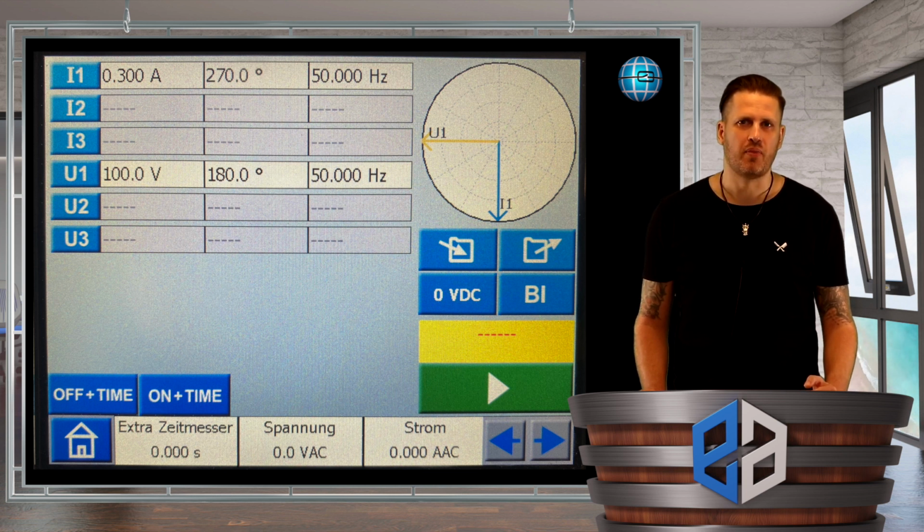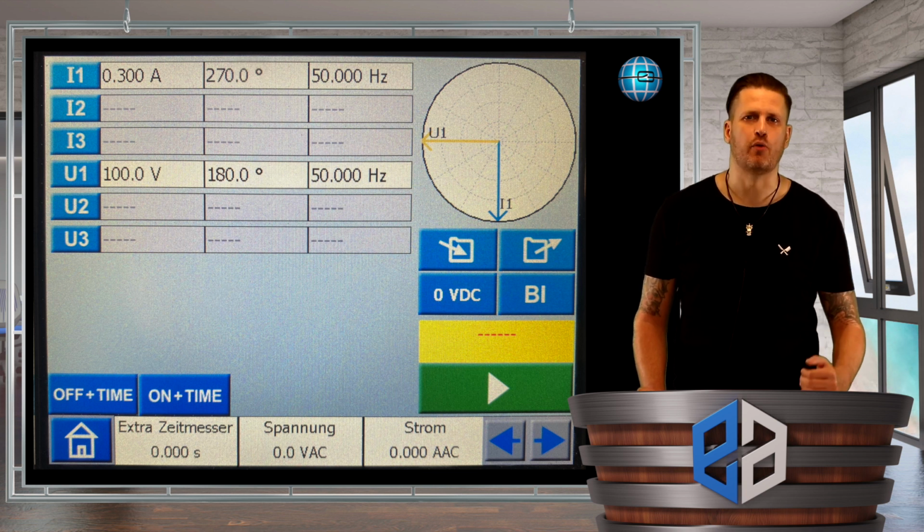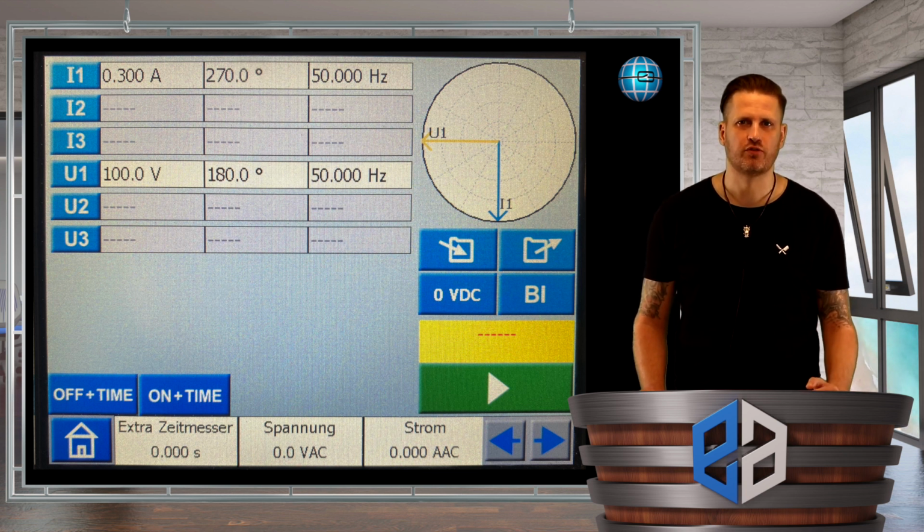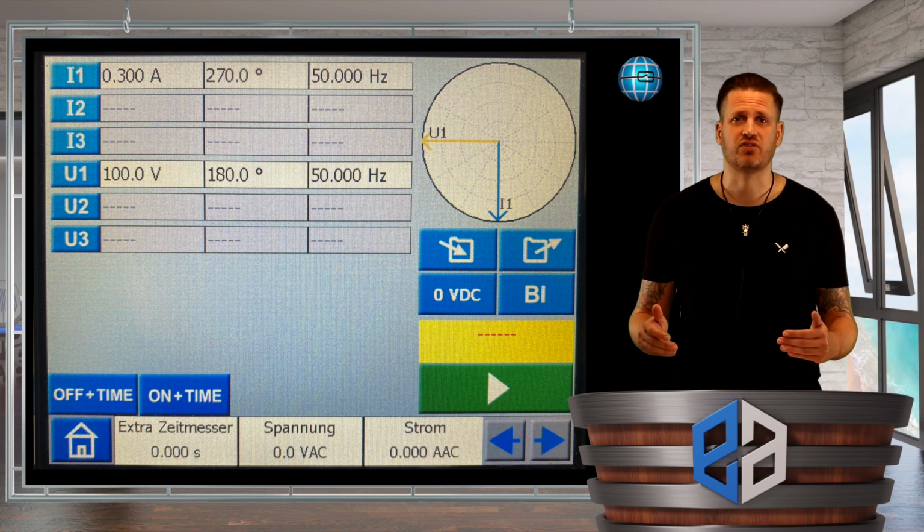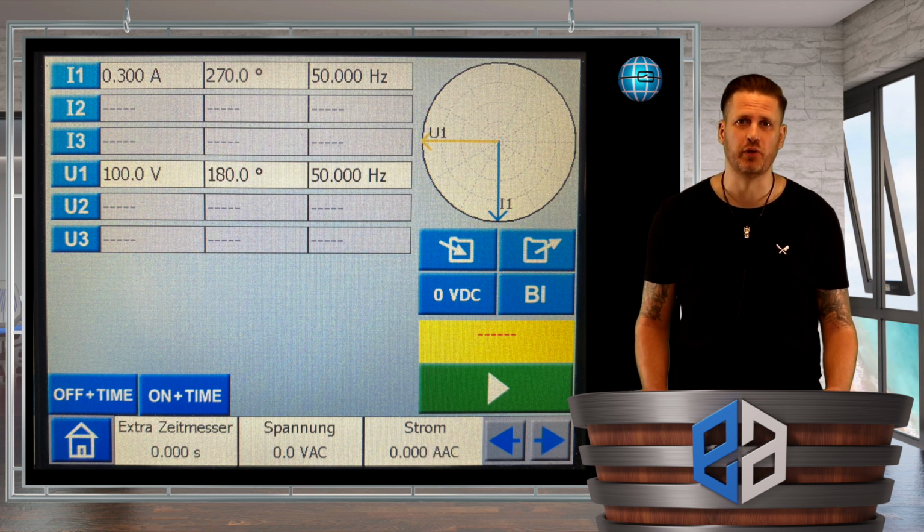We remember the theory: the capacitive ground fault current of the faulty feeder flows in reverse direction through the current transformer and appears as an inductive current. Accordingly, a current lagging by 90 degrees must trip, and a current leading by 90 degrees has to stabilize the directional algorithm. Here we go.